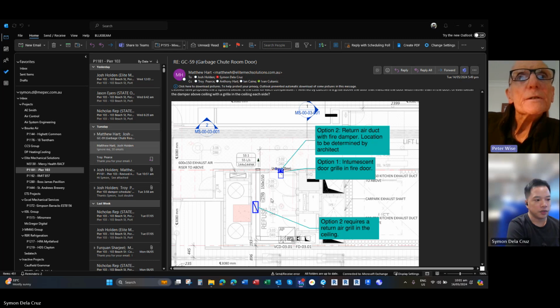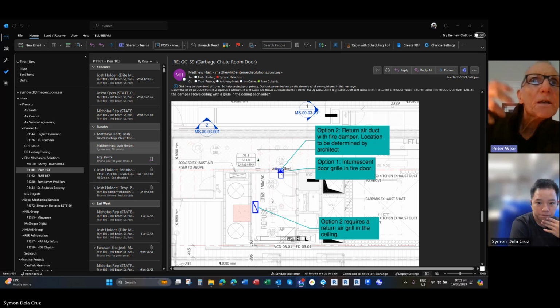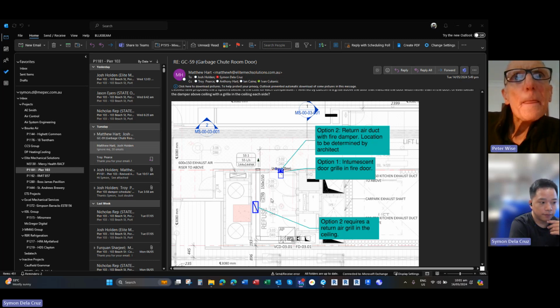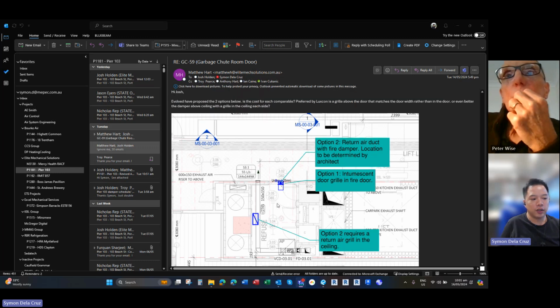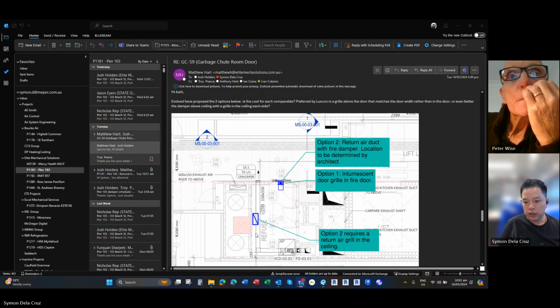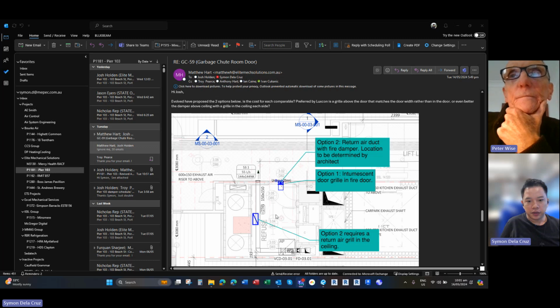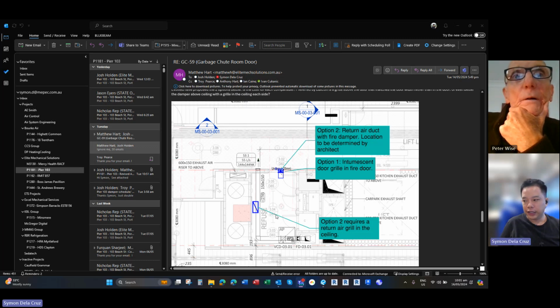So you're getting the air coming through the door opening, but also through this grill, is it? Yep. This is above the ceiling, and this is the ceiling grill. So it will just go down and suck. But if you have opened those garbage chutes too. Right, so we are arguing if I need to assume 160 for the return air, for the grill, or 80.